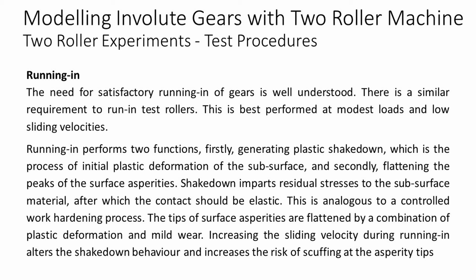The tips of the surface asperities are flattened by a combination of plastic deformation and mild wear. Increasing the sliding velocity during running in alters the shakedown behavior and increases the risk of scuffing at the asperity tips.